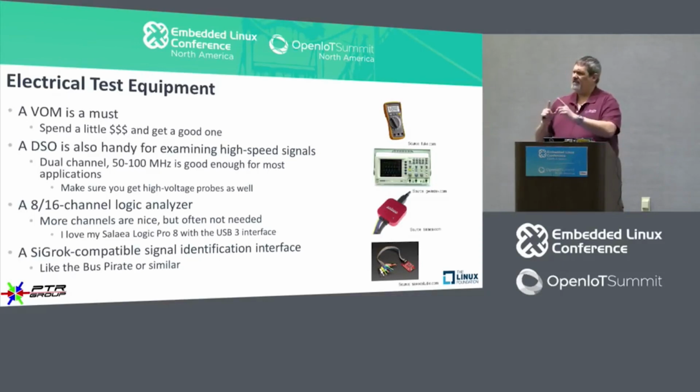Now, some of the little PC scopes that are USB powered, some of them are not quite fast enough because they're only in the 5 megahertz, 10 megahertz range. Usually 50 megahertz or so will allow you to catch most things that might be of interest.